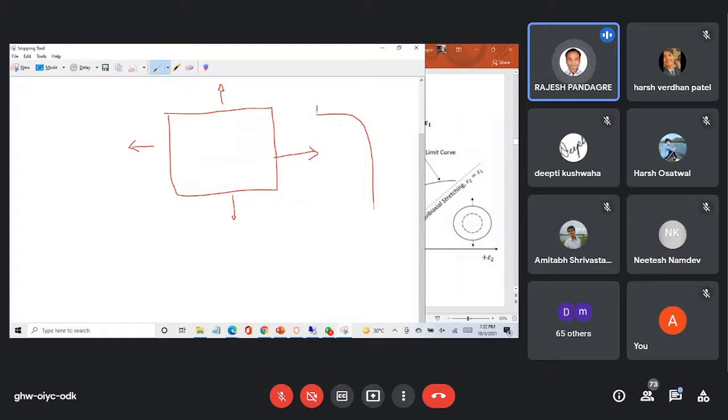You know this bending curve also. This area is called the compression zone, this is called the tension zone. Everyone knows it. So whenever the stretching is happening, means tension is happening there. And wherever the thinning is happening, thickening is happening, material is getting thick somewhere. So thickening means compression is happening. Because of compression, thickening will happen, and because of thickening, wrinkling is happening.